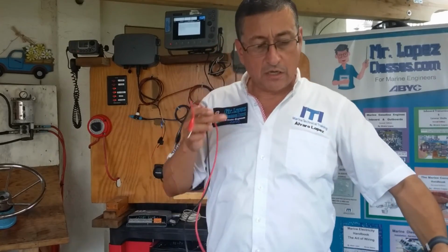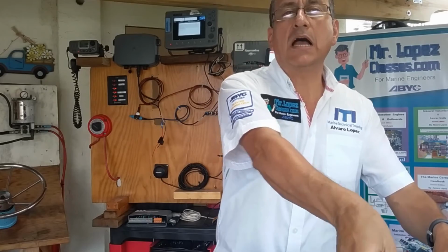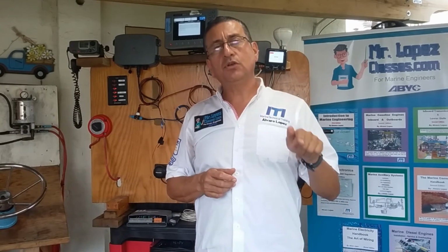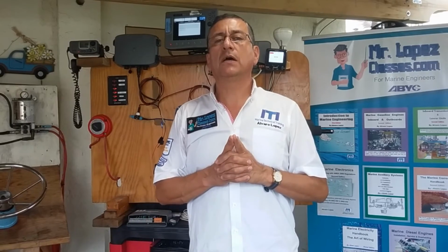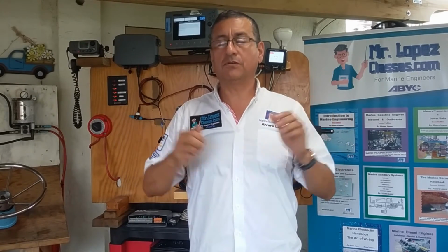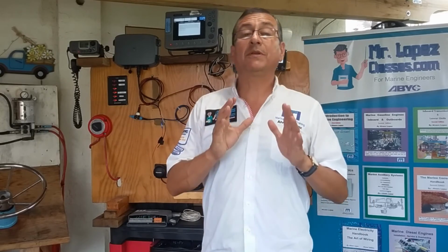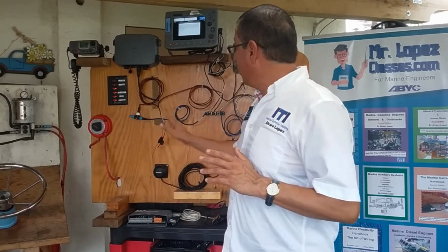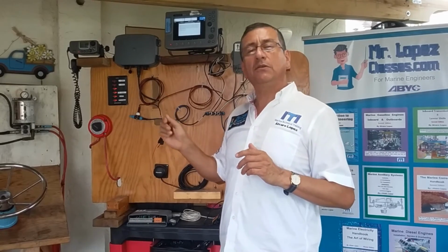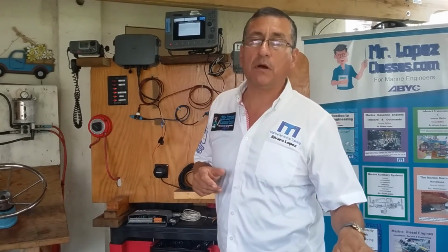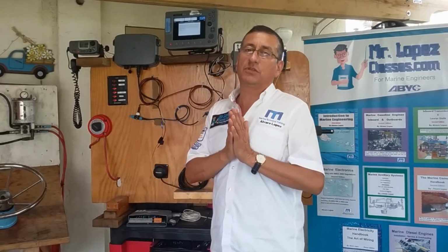In some boats, the engineers prefer to install constant sources of DC power. I prefer the batteries, because those constant sources of DC power depend on AC sources of power. They depend on the generators. In that case, I prefer to install from those. The recommendation is no combinations. Okay, if all of the power inputs are from batteries, they should be from batteries. If all of the power inputs are from sources of power, use sources of power. That's your decision.